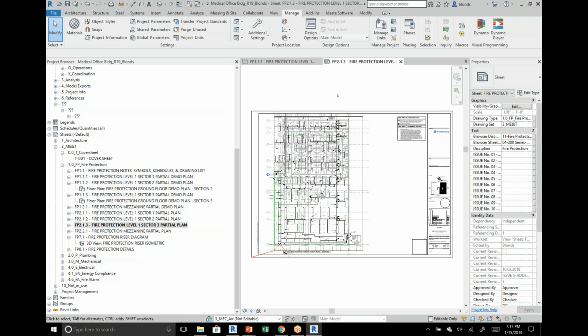Yeah, I did the exact same thing, and I tried both ways. Right? You open up the title block, drop the lines in there, save and reload it, and it shows up on every sheet whether you want it or not. And then you can reverse that and make sure you get them. What I usually do is paste a whole bunch of selected views, and I get all of the views at that height, and then try to remember to complete them as I go, and invariably miss one or two. And then I'm amazed that nobody else looks at it and wonders why there's this red line.